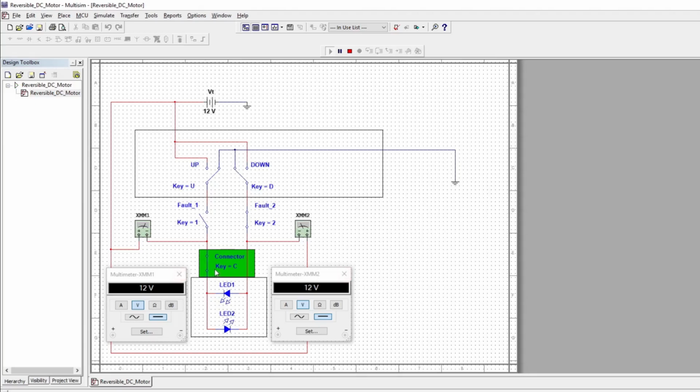So this is why I state, and this is why I have this connector here in green. We're going to open this connector now. This is why I state you have to unplug and isolate that circuit. Now you see, as soon as we unplug that connector, this went to 0. It in fact doesn't have a path to ground. It was backfeeding through the motor.